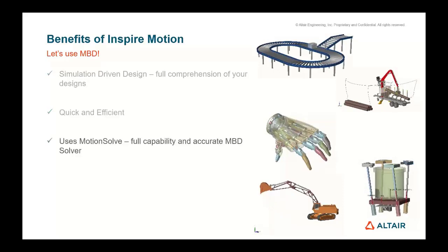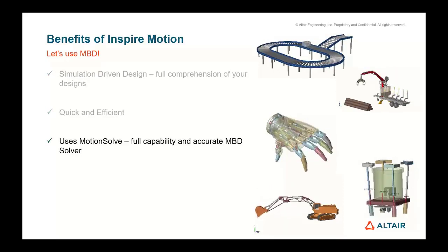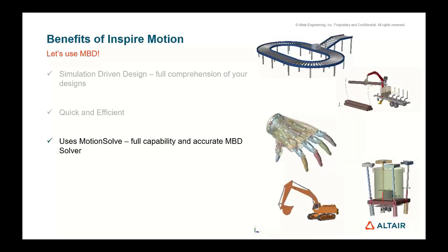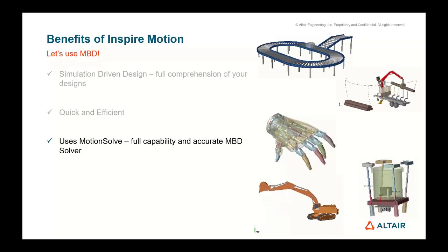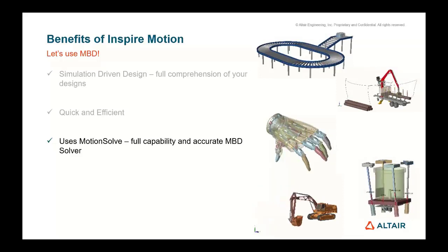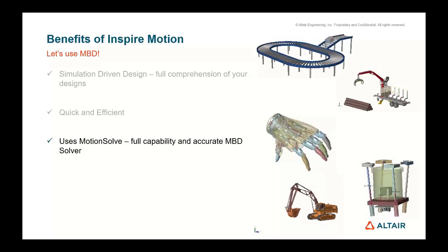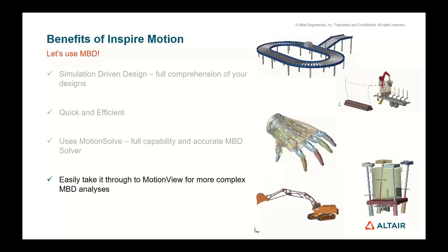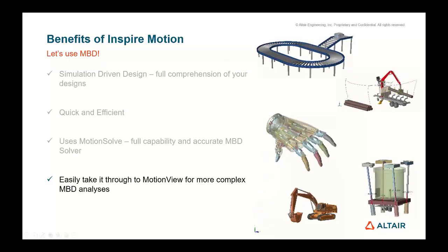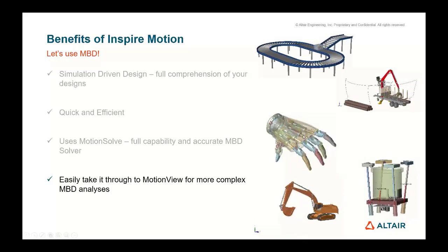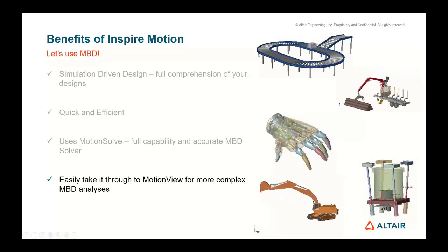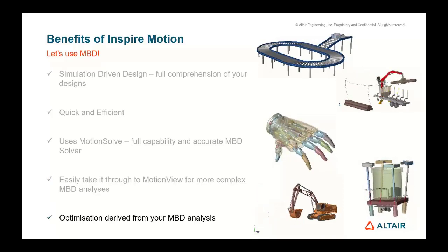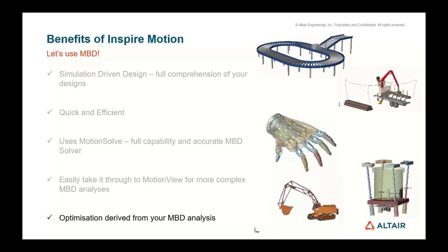It's quick and efficient. It uses Motion Solve, so this is our full capability and accurate MBD solver. So it's just a different GUI to Motion View, but in Motion View you can look at more advanced aspects of multibody dynamics. However, both of them use the Motion Solve solver in the background. It can easily take it through to Motion View for more complex MBD analysis. So if you started off in Inspire Motion, it is a database that you can export out of Inspire Motion and open in Motion View instead. And of course, you can start doing optimizations that are derived from your multi-body dynamic analysis.